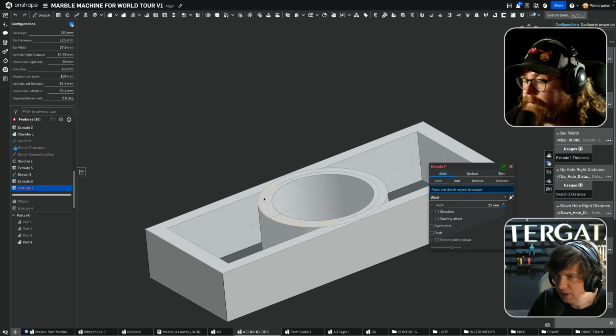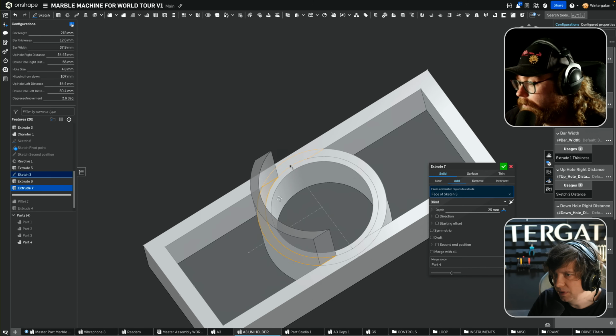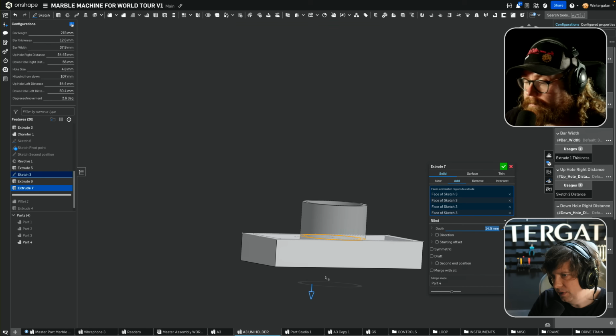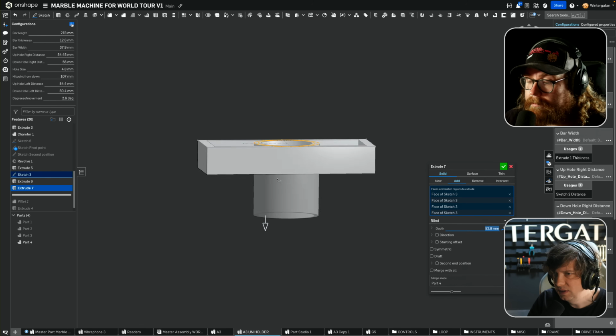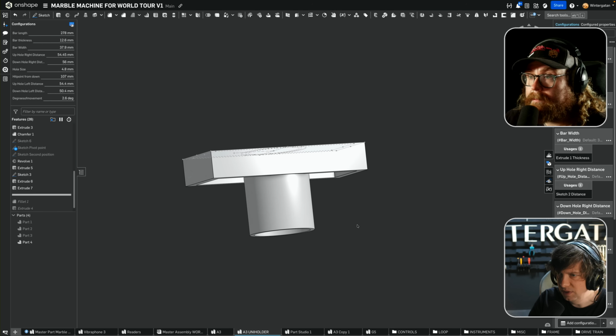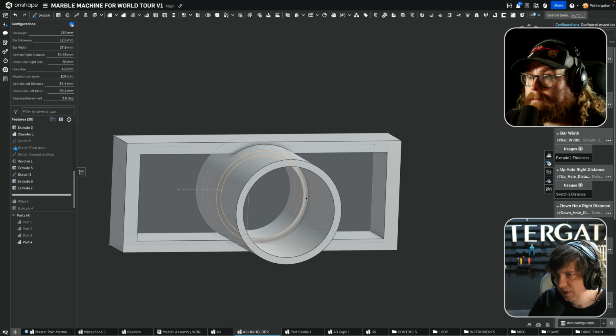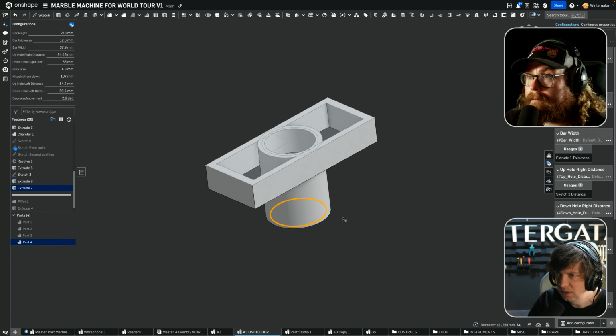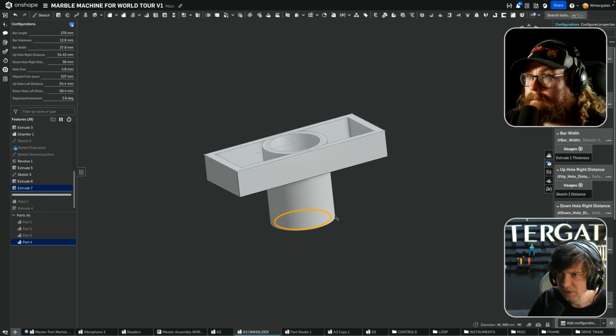Then we're going to extrude the sleeve that the PVC pipe is going to slot into, which is this one. And we're doing that like this. Someone said 4 centimeters. Let's go with 4. So here you can see the PVC pipe is going to slide up exactly until this end here. And this is 40 millimeter, correct. We're still going to do these nice fillets.